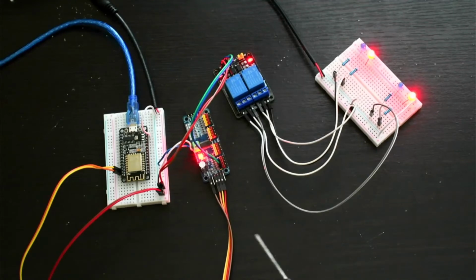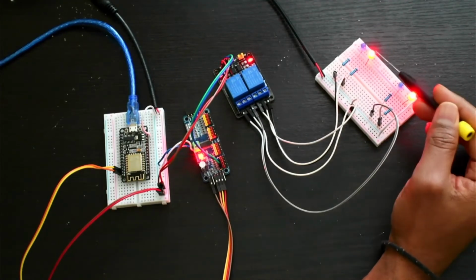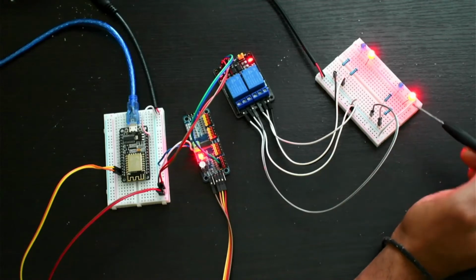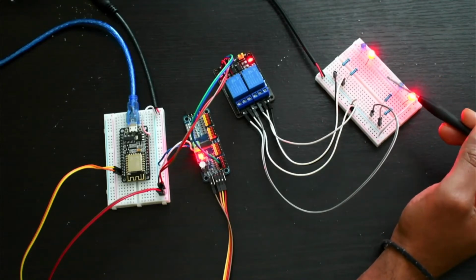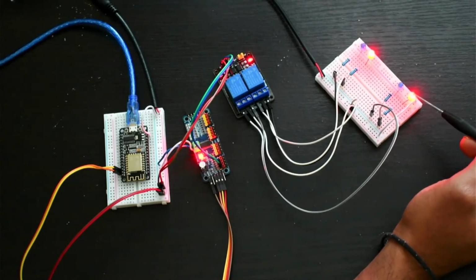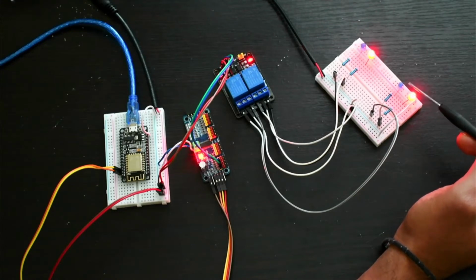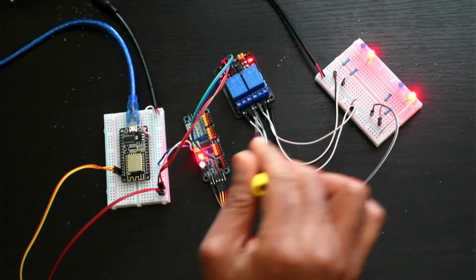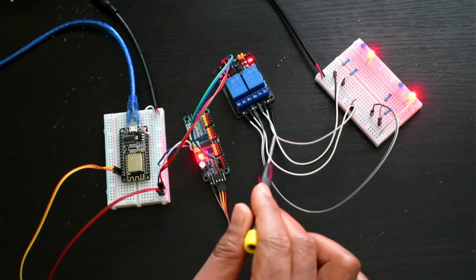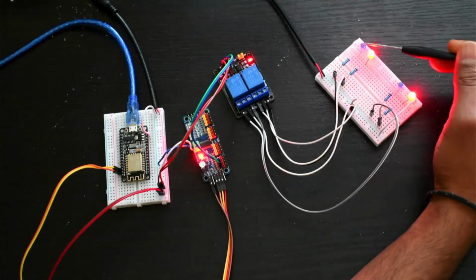Once you connect everything, you can see the side where the LED is continuously glowing. You should never put your turnout towards that side. The reason is that every snap turnout needs power just for a few milliseconds, and if you continuously power it, it will burn out immediately. Just to save it, you should always test it like this first, and based on that testing you will identify which side you have to configure.